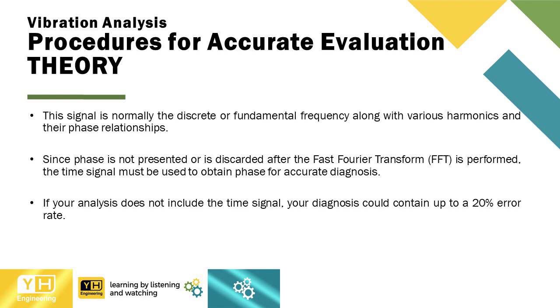Since phase is not presented or is discarded after the fast Fourier transform, or FFT, is performed, the time signal must be used to obtain phase for accurate diagnosis. If your analysis does not include the time signal, your diagnosis could contain up to a 20% error rate.